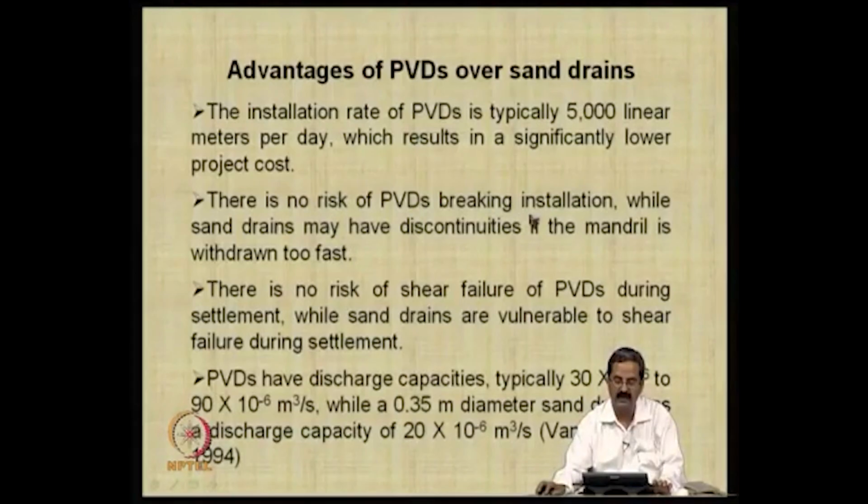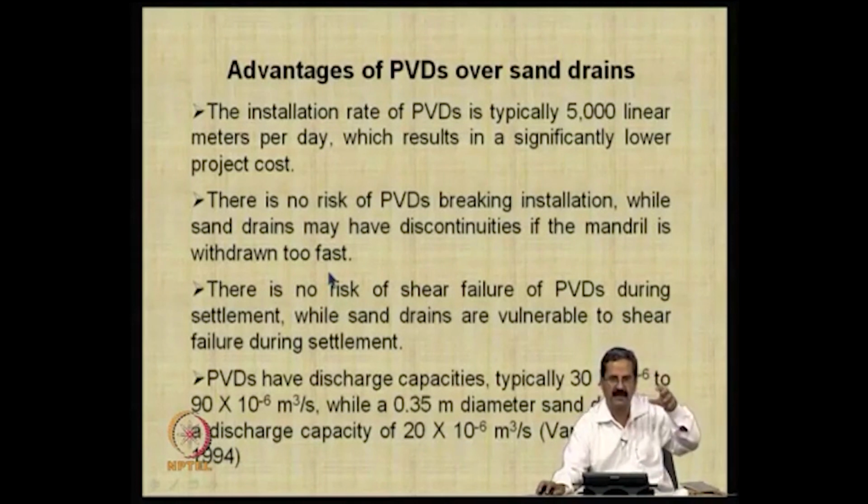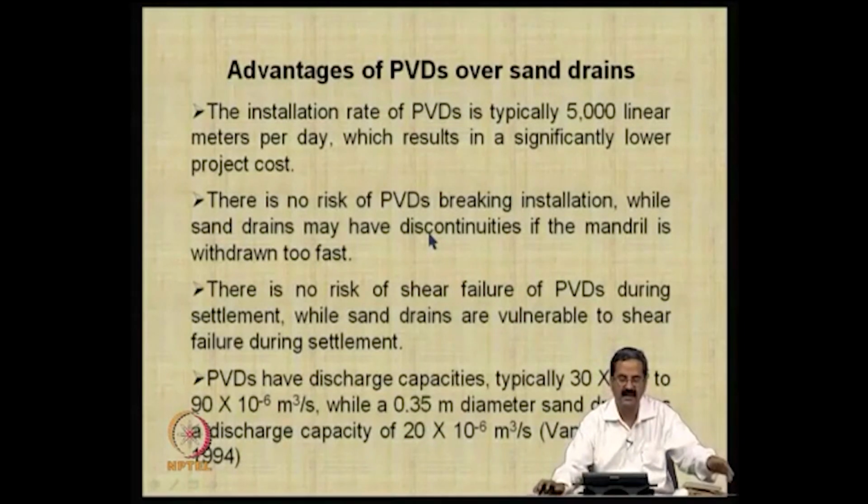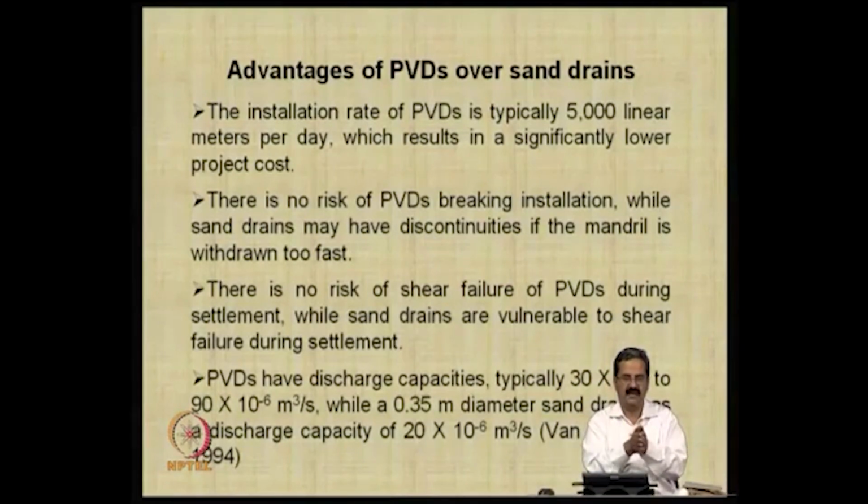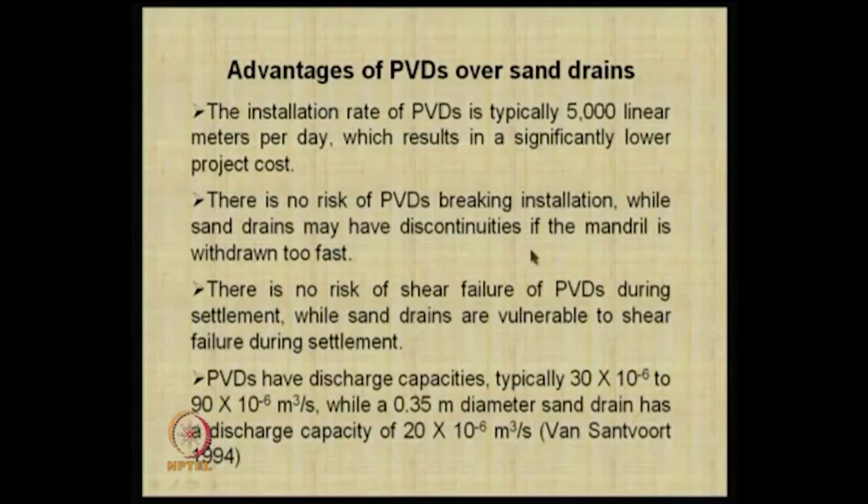There is no risk of PVDs breaking or losing continuity, while sand drains may have discontinuities if the mandrel is withdrawn too fast. If you remove the mandrel, the problem is that sand is a weaker material; it fails by shear, so shear strength is somewhat important, and sand drains may develop discontinuities in the process.